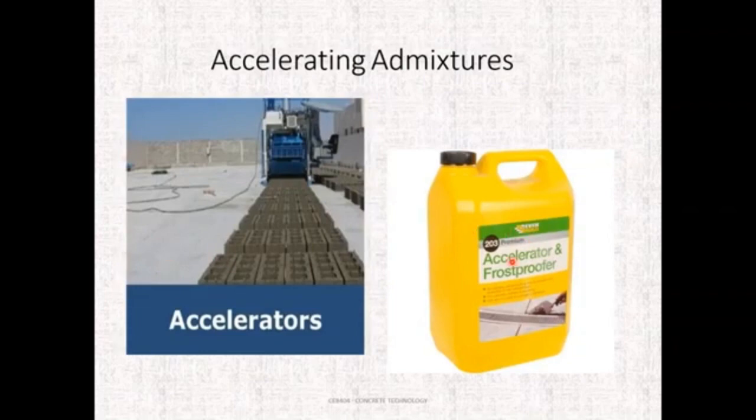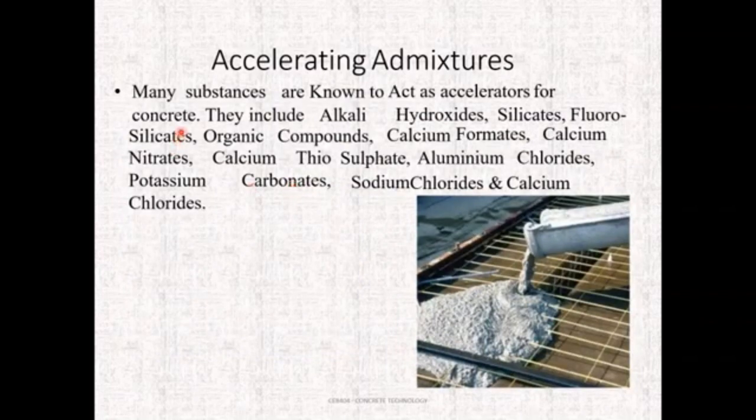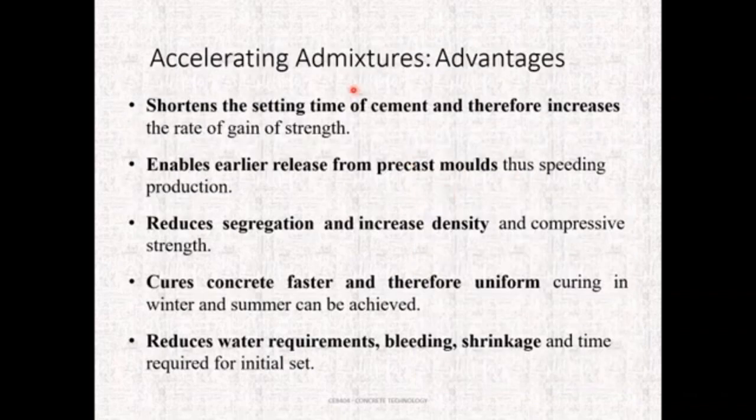Generally, accelerators are used in precast elements to increase the setting of the concrete. The commonly used materials are alkali hydroxides, silicates, fluorosilicates, organic compounds, calcium formates, calcium nitrate, sodium chloride and calcium chlorides.